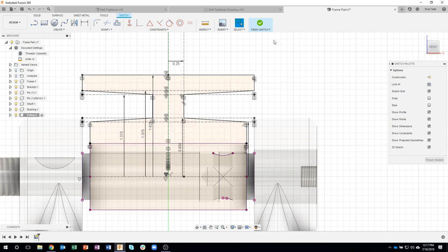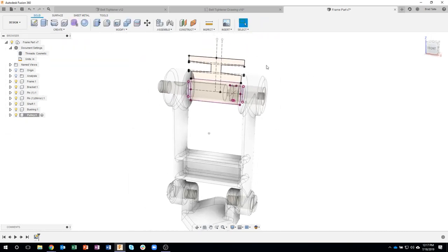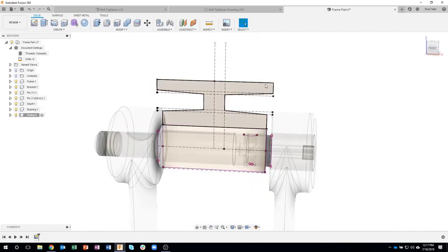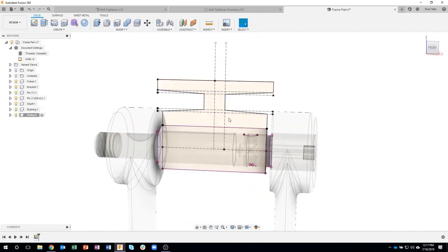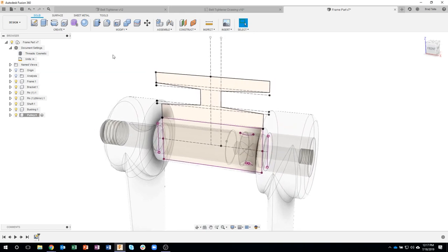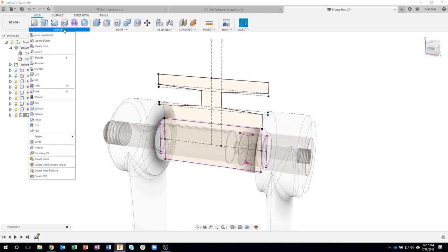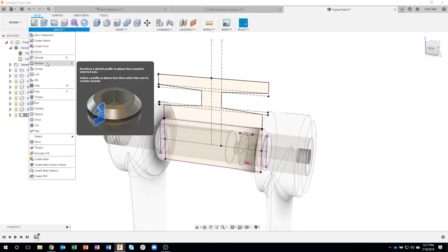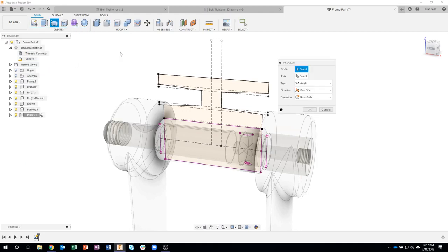Okay. I'm going to go ahead and finish my sketch. Let's zoom up here a little bit. And like I said, this was probably one of the more complicated ones. It was basically because we had to create a bunch of light pencil lines to help give us our profile that we needed to trace over. So now I'll come into my Create menu, and instead of doing an extrusion, we want to revolve around an axis. So I'll say revolve.